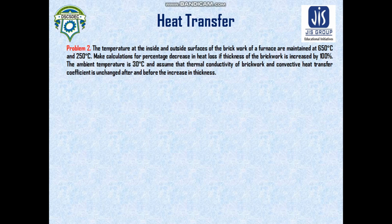That means the bricks had an initial thickness, and in this final case its thickness is getting doubled. The ambient temperature is 30 degrees Celsius, and assume that thermal conductivity of brickwork and convective heat transfer coefficient are unchanged before and after the increase in thickness.